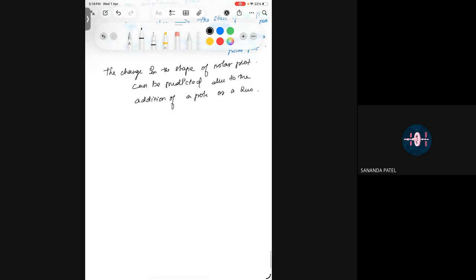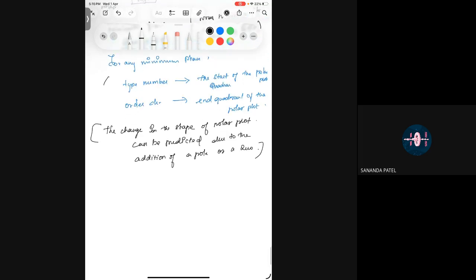Okay, fine. Remember this one and the above one here. I'm going to tell you a basic rule to start and end, or to draw the polar Nyquist plot. I will stick to the term Nyquist plot to avoid confusion. Now, if I want to draw a Nyquist plot for a system like this, (S plus B) by (S plus A), where S plus A is a pole, and the pole lies at minus A. This is your zero, this is your pole. We all are clear with this, right?